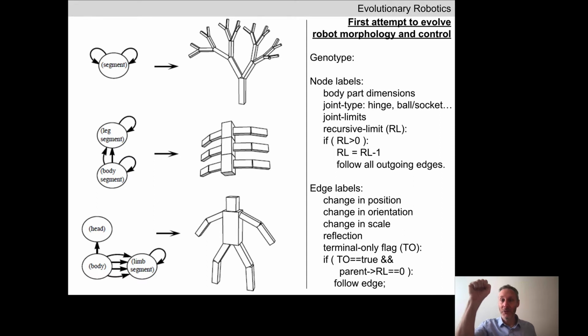As you probably figured out already, in your body.urdf file, the bodies are encoded as trees, where we have the base as the root of the body. And then every other body part making up your robot has information about that body part and also information about the joint that connects that body part back to its parent body part. The body part is an upper leg, like in the quadruped. The parent body part is the base. If the body part is the lower leg, the parent node is the upper leg, right? Information that's flowing up towards the root of the virtual creature.